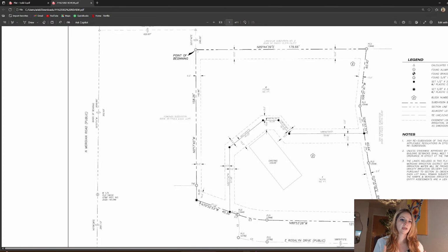There are multiple different ways for them to describe how land is done. Many times it will be a walk-this-way method. So it says, this is the point of beginning, and it's a well-established point, whether that is a pin in the ground or a monument of some sort that they can reference. So they will start that way, and they will say walking due north 427.6 feet, and then turning due east and walking another 2,000 and I don't know, just any kind of